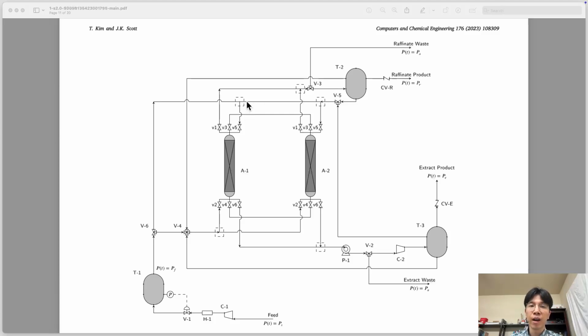That's important, valve 5. Whenever material is going into the adsorption column from the top end, it is going through valve 5. And you can see, going back to valve 6, when the flow from the feed tank is diverted and goes to the top, it gets fed into valve 5 again. So there's a mixing point, and it goes across valve 5 and gets fed into the adsorption columns. So flow into the adsorption column from the top end is always through valve 5.